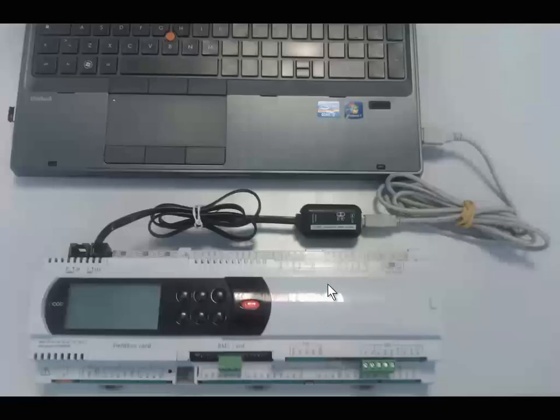Well, here is bigger. So you have to use a USB to RS485 converter. USB this side connected to any USB port, and on the other side RS485 to this terminal of the Pico. Don't confuse this terminal to the one on the left, because it is for a completely different purpose. So normally here there is the terminal, so disconnect the terminal and connect the converter to the PC.